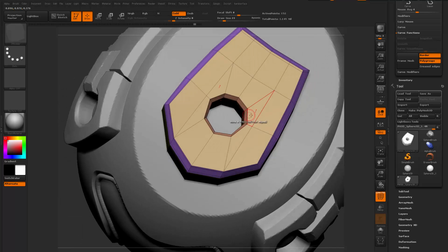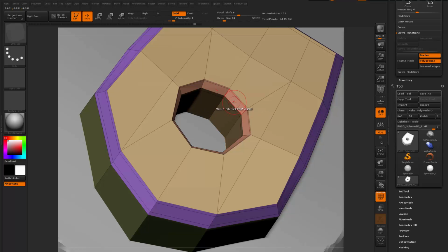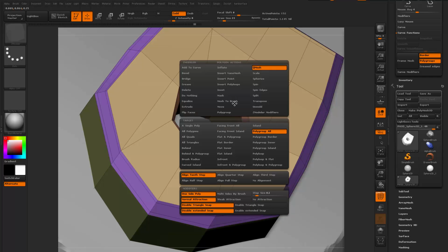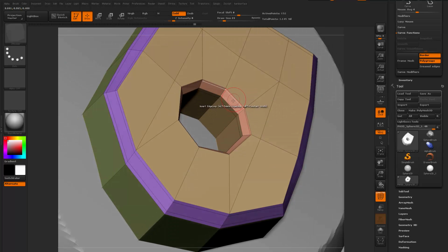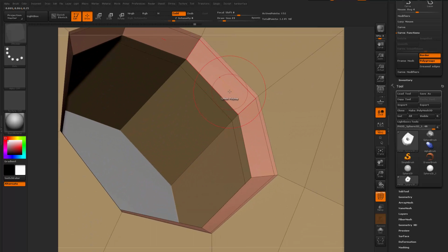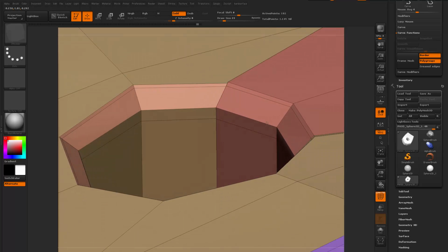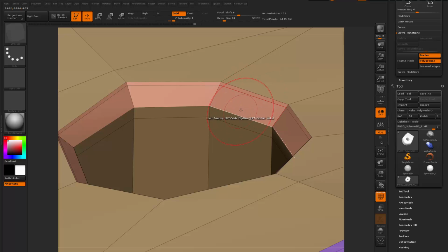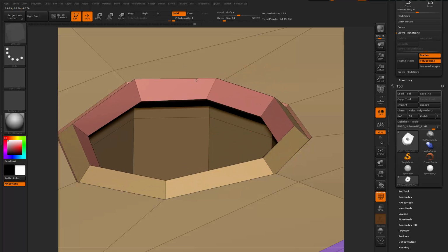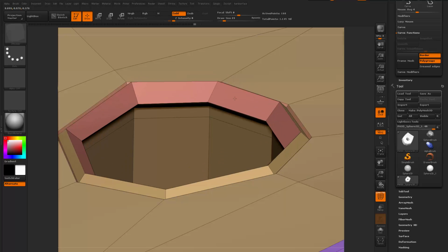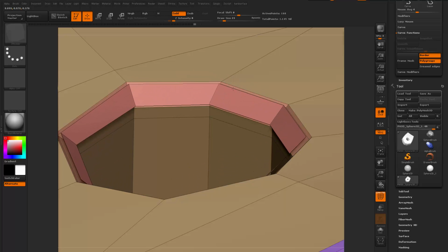Let me do something here real quick. I'm going to use Q mesh and Q mesh this loop out, poly loop, and then with poly loop you can choose which direction because every face has 2 directions. You see those 2 yellow lines? So that's one of the directions. Okay, that's another direction. So when you're Q meshing things out, you can hold down Control. That's going to perform a duplicate face.